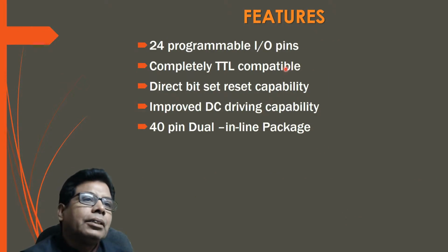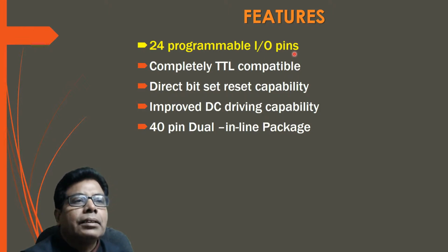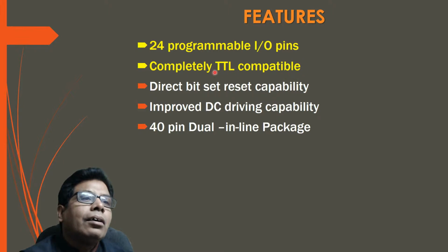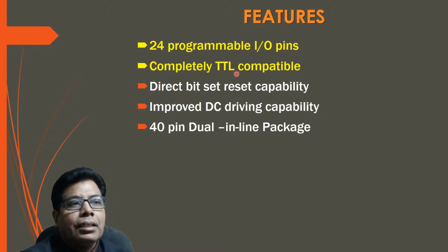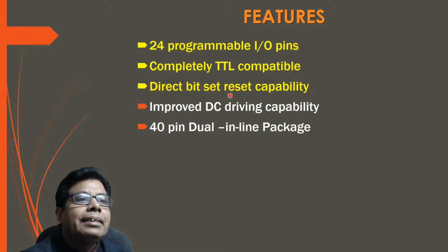Then let us see the features of 8255. There are 24 programmable I/O pins in 8255. Then it is completely compatible with TTL. Then direct bit set reset capability, so it has the capability to set or reset a bit directly. Then improved DC driving capability, so it provides sufficient current for driving the load. Then 40-pin dual in-line package. It's an IC available in a 40-pin dual in-line package.